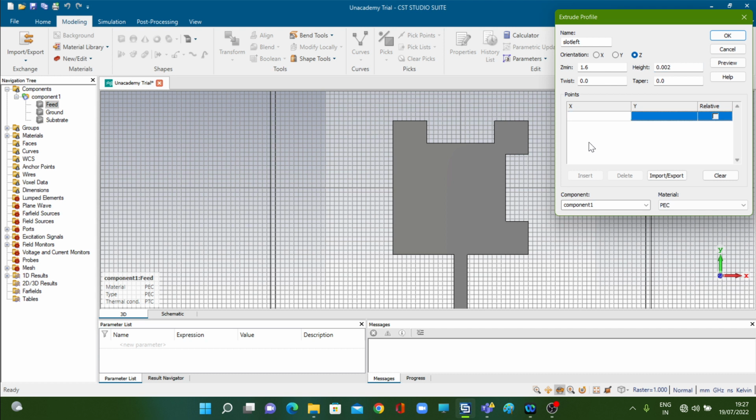Now we will define the points. See, let us select the point here. Now this point is on the second quadrant. So X will be negative, Y will be positive. Let us select X to be minus 15, because we are considering a point at the extreme left hand side edge where X coordinate is minus 15 only. So minus 15, tab. Now not 15 but somewhat less. So we take the same value, 7.5. Enter. So this point is selected.